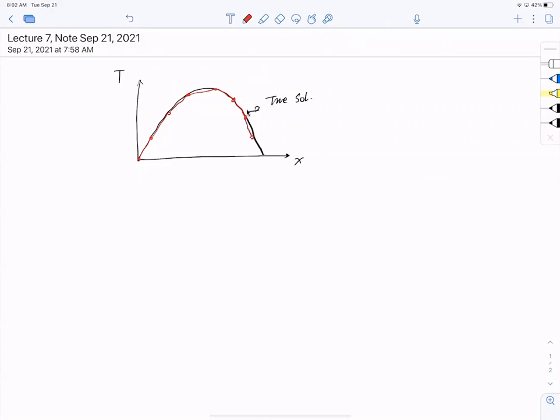Okay, so these are the lines where we call finite element solutions. Now, if you're trying to find errors, what we can do is pick at least 5 points within each element, 5 points within each segment, and so on and so forth. And I want you to compute the sum of the error at these points divided by the total number of points you have. Let's call this the average error.